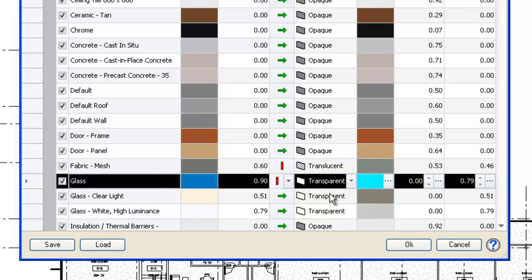This is done automatically, as ElumTools will search the Revit materials for the word glass and apply a transparent surface type to all positive search results. ElumTools then assigns the Revit Graphics Transparency property to the surface, as well as the Revit Graphics Color to approximate tinted glass. There is no correlation between graphics color and graphics transparency in Revit. However, ElumTools uses the graphics transparency value and then attempts to find a similar color, say blue, that can have a calculated transparency of the same amount.